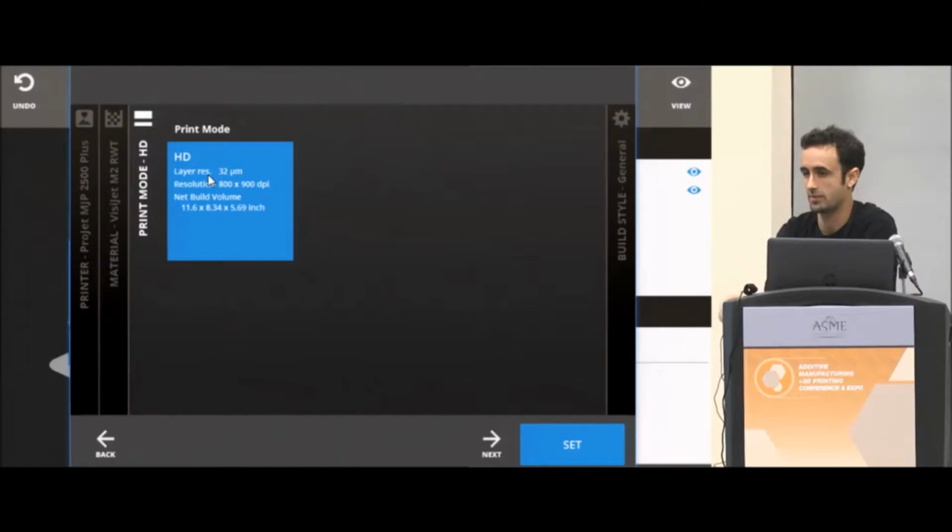One of my favorite surface finishes is actually a combination of printing and machining. You print almost the entire part with a little bit of stock around the edge, and then machine off that stock very quickly, like one pass. Then you can get the tolerance back down to something perfect and a nice, beautiful machined finish, versus the layering of a metal print, for instance. Ours are fantastic, but it's not a perfectly glassy, smooth machined finish. But it's easier to normalize the surface quality than it is to very specifically change it in one area. It's a good question though. I would like to do more experimenting with that.